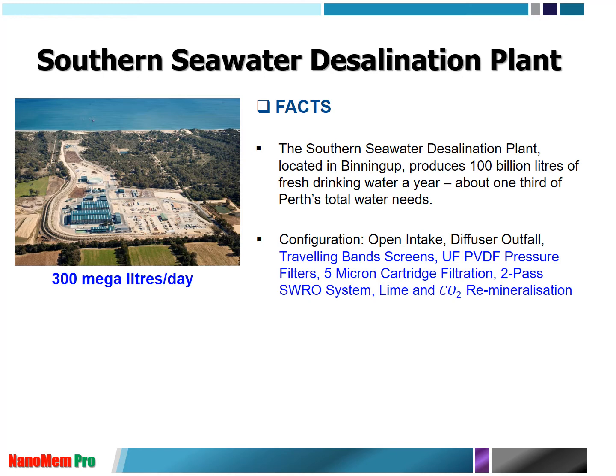So what is the difference between these 6 desalination plants? Mostly they are very much the same for SWRO. They all use SWRO as the main desalination technology, with a little bit of difference in pretreatment: one is ultrafiltration, the other is dual media filtration. There is also a little bit of difference in post-treatment. Some places just use CO2 remineralization, some use lime and CO2 remineralization, and some other places incorporate lime, fluoride, and CO2 remineralization.